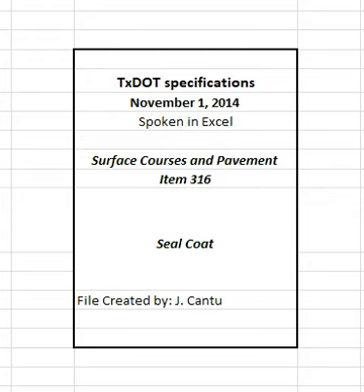4.4.1 Standard temperature limitations. Apply seal coat when air temperature is above 50 degrees Fahrenheit and rising. Do not apply seal coat when air temperature is 60 degrees Fahrenheit and falling. In all cases, do not apply seal coat when surface temperature is below 60 degrees Fahrenheit.